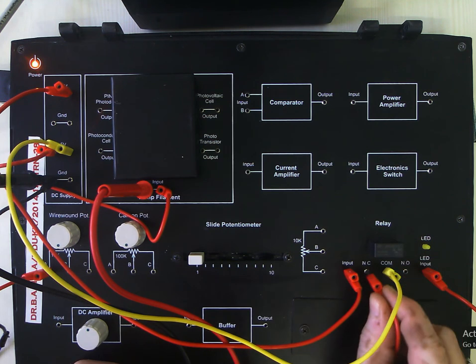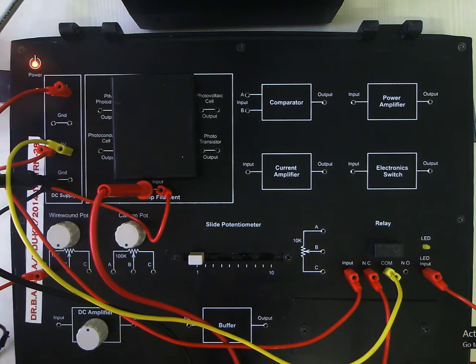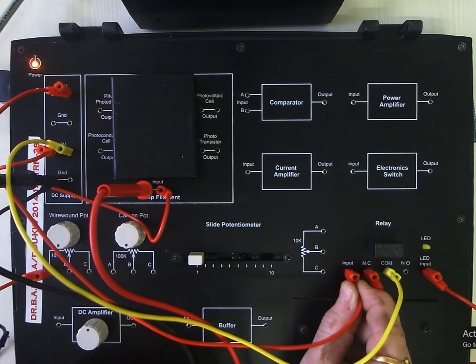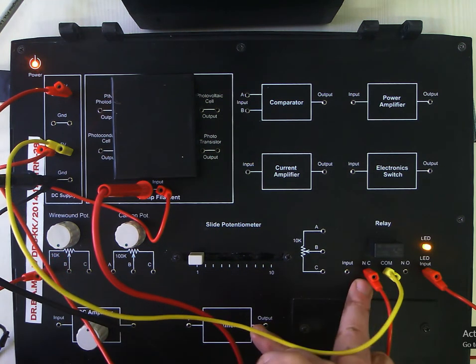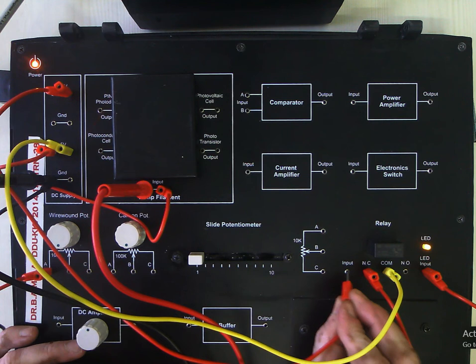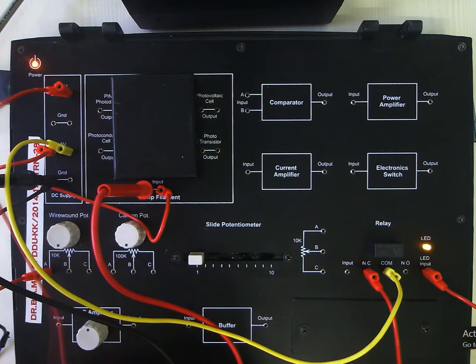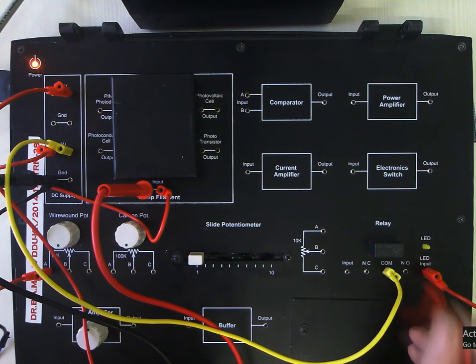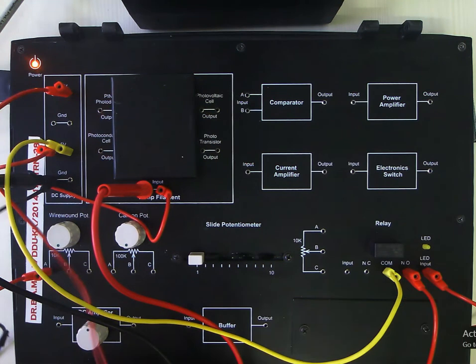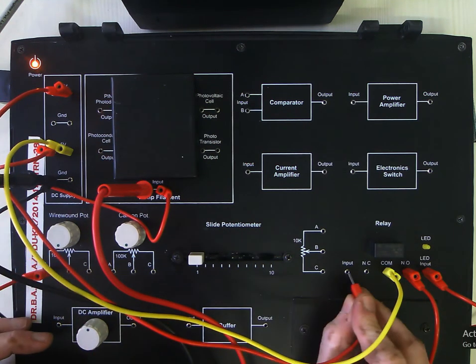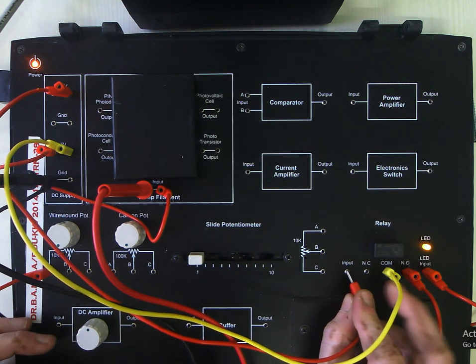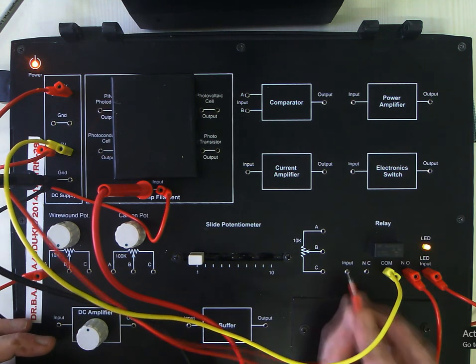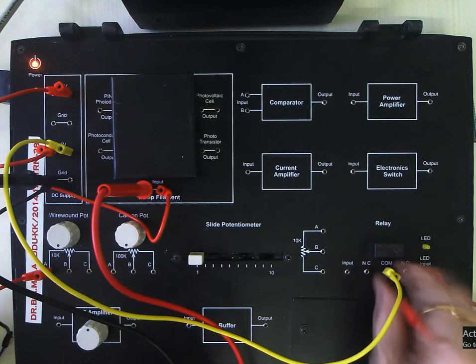if I connect it to the NC and I de-energize the coil, you can find the LED is working. Why? Because the common terminal is connected to the NC. I will put the input, it is off. Now I am connecting the LED to the NO, that is normally open. When I apply the input, you can find the LED works. Now this common terminal, which is having 5 volt, is connected to the NO.